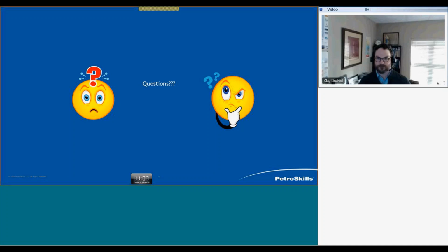I didn't really address it in the webinar, but one of the problems that you're going to come up against is that when you get a piece of equipment, you're going to have many types of failures, and you're not going to get 20 failures of the same type. And that's why we've been forced into using things like Weibull. The problem is once you start using failures from different root failure modes, then you're twisting the data and the data's being deformed and it won't tell you as much.